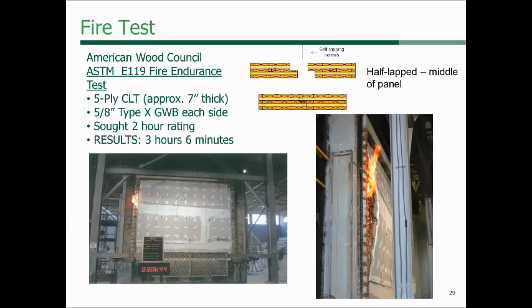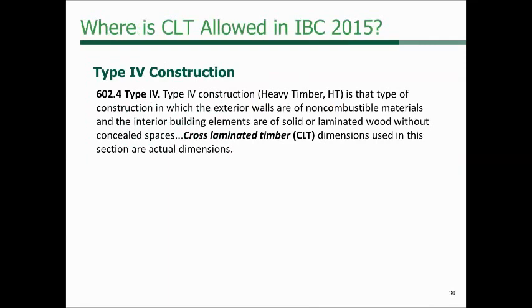And as you can see, the only reason why the test was stopped was because of the breach between the drywall and the cross-laminated timber. But the cross-laminated timber still had a lot of fire resistance in its wood product. It didn't fail structurally under the fire test.